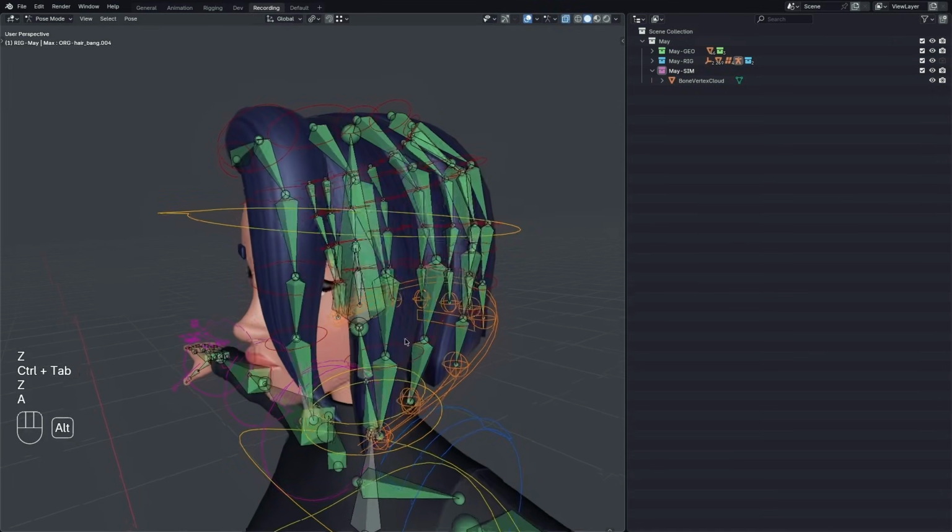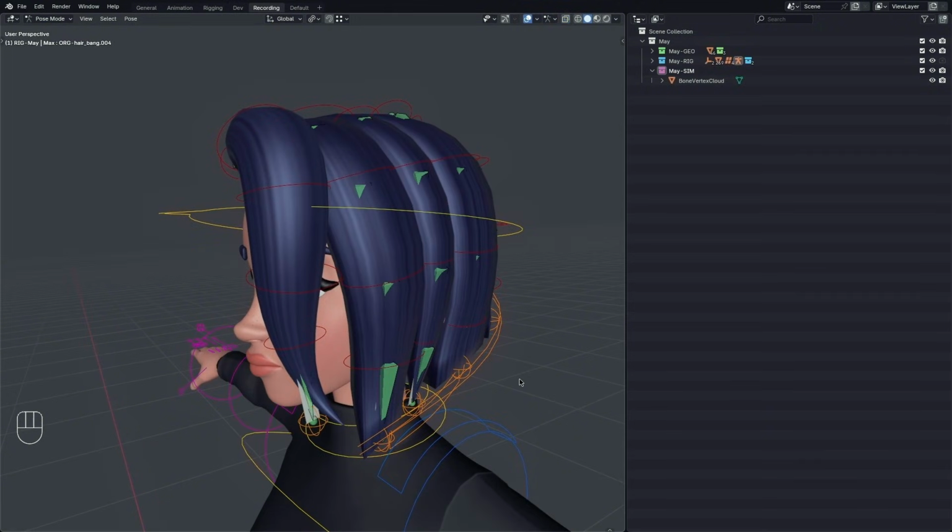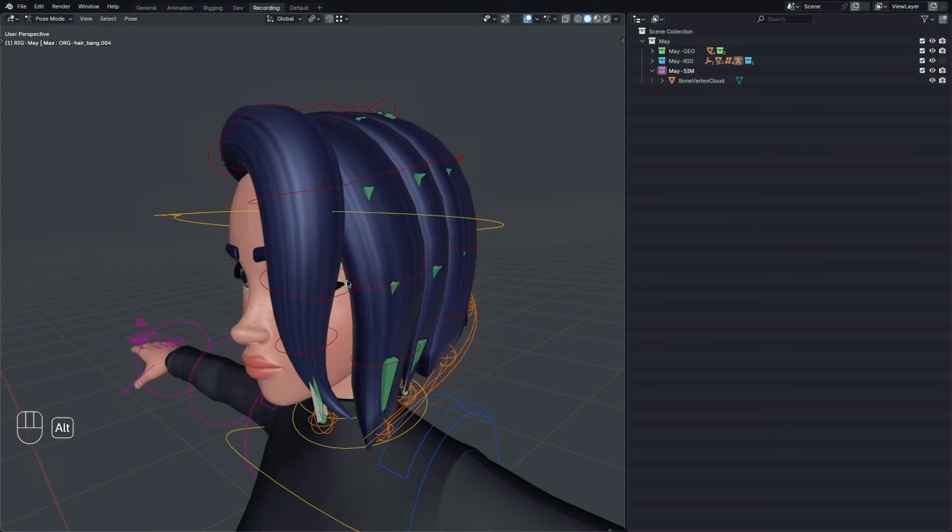We're going to deselect these bones. And now we're going to use another script to generate empties at the same locations, the head and tail locations of each bone, so that we can then parent those empties to the vertices on the new object that we just created. That way the empties will be able to follow along with the simulation. And then we're going to use another constraint on the controls themselves to constrain the controls to those empties.